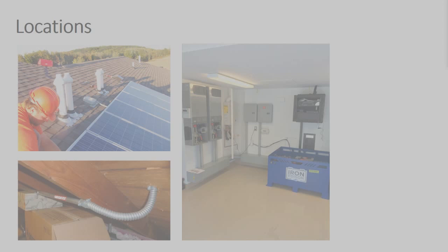Inside your conduit, inside the attic, where you see this conduit going up to the rooftop. Well, that conduit is not just in the attic; it's going up to the rooftop, and we'll see code requirements that say at that point you need to put foam sealant into that conduit, because what can happen is the temperature difference between the attic and the atmosphere can cause condensation and moisture, and water can get into that conduit.